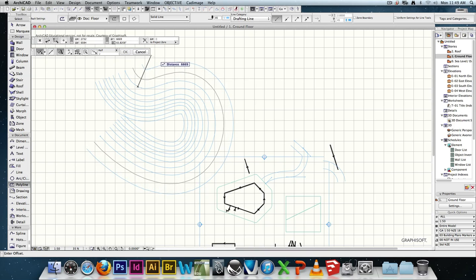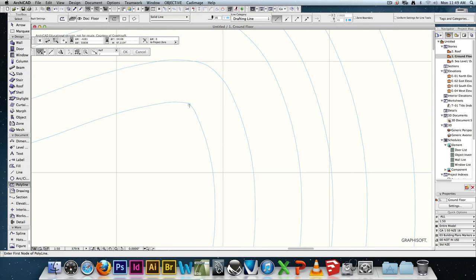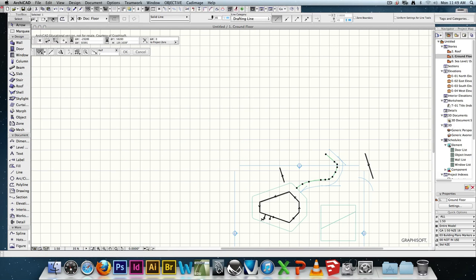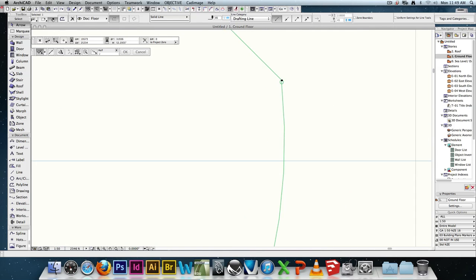Also, this is strange, isn't it? Why is it doing that? Yeah, very peculiar, because it's just offsetting edges. So now there is a workaround to this. I needed this to be 1500, I couldn't do it. See, and it's done the same thing here. All it's done is reduce this radius down and down and down until eventually it can't go any smaller. So how do I deal with it? I'm just going to undo, undo, undo. Oops, sorry. Redo. What I'm going to do, so I still need this to be 1500. I've got a little problem because that's happening.